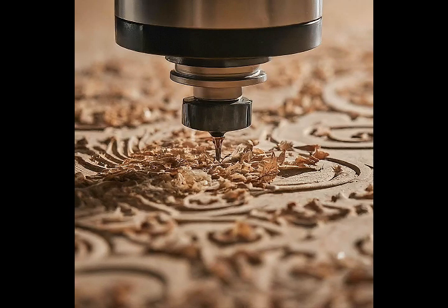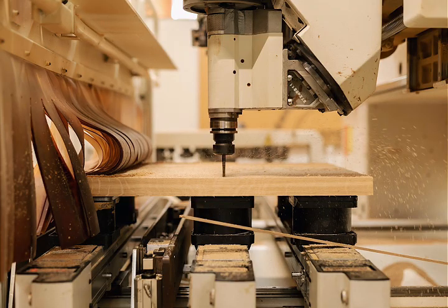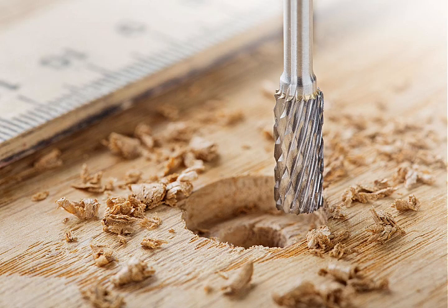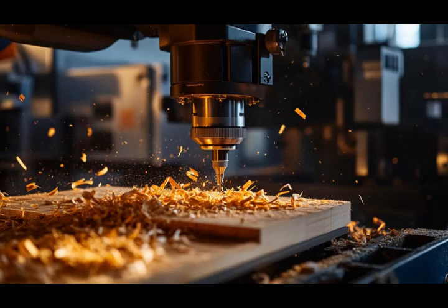What are CNC cutting parameters? Cutting parameters are the values that control how your CNC router removes material. The most important ones include spindle speed (RPM), feed rate, plunge rate, cutting depth, step over, and chip load. Every successful machining operation depends on balancing these parameters correctly. Changing just one value affects all the others. That's why experienced CNC programmers always think of cutting parameters as a complete system rather than individual settings.